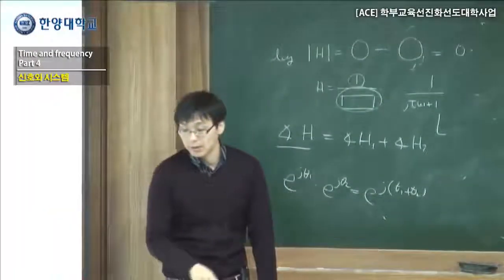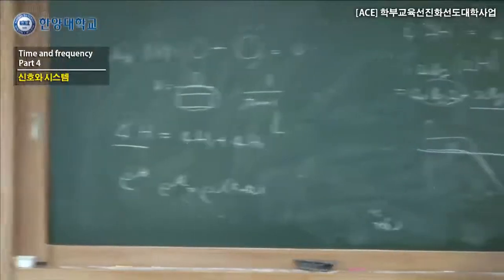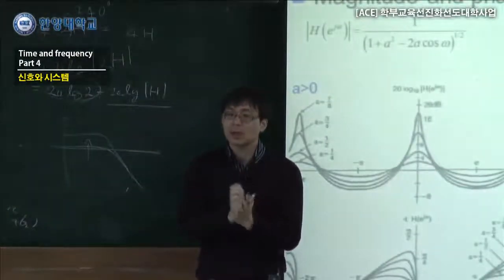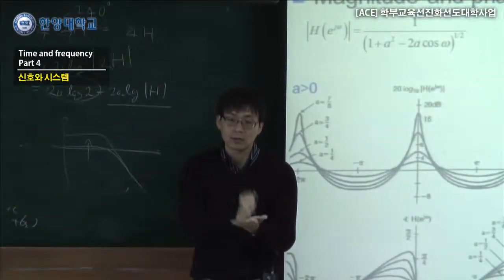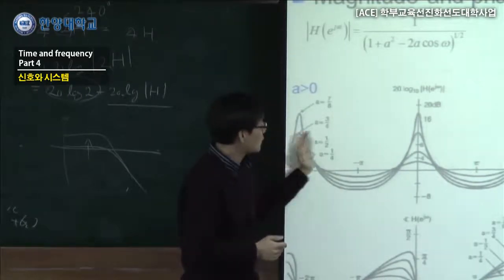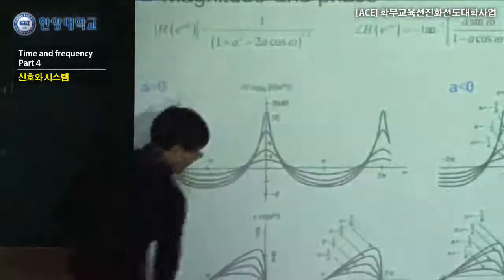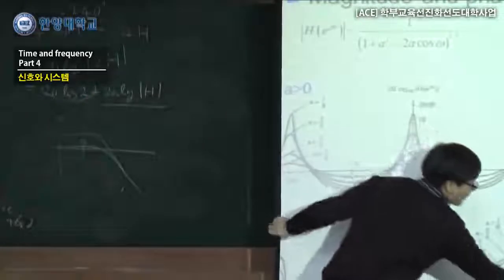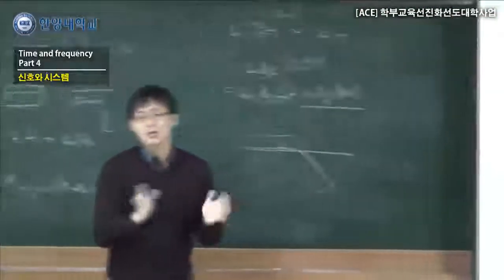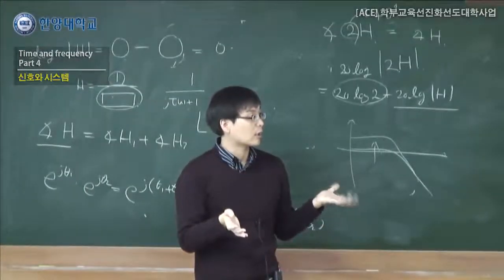When you plot its phase and amplitude, as I said, in case of discrete time Fourier transform, they are continuous in frequency and periodic in frequency. So they keep on repeating. The amplitude is repeating, and the phase is also repeating by a 2 pi period. So it does not have much meaning when you draw the Bode plot in discrete time Fourier transform.